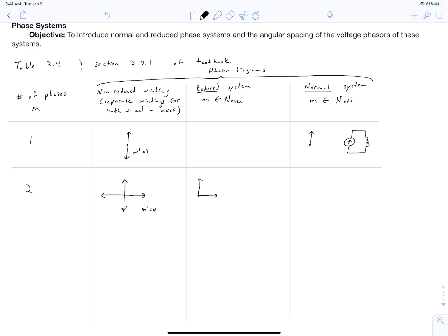And if we talk about how we connect to it, we can sketch our coil groups, or our phase windings, like this. And hypothetically, this is not the right answer, but if we were to try to connect to it without using the neutral point, you'd see that it's impossible. Any current that we would inject into this terminal has to flow out over here, and so these two current sources are incompatible. They would fight each other. And so the way that we actually have to connect to it is as follows.